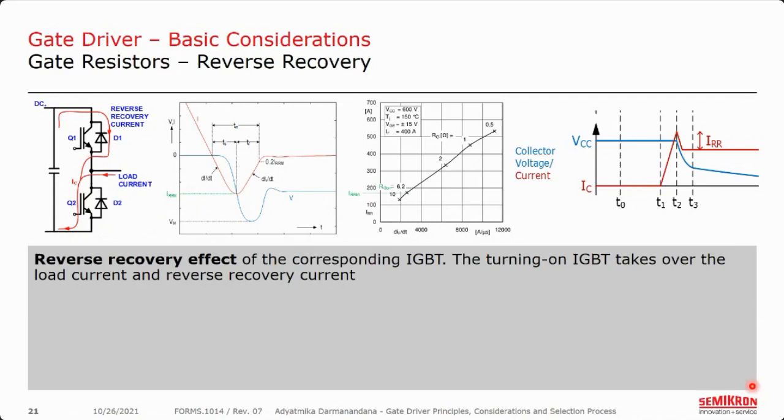If we take a look at the IGBT Q2, the current will be reflected into a peak at the end of the ramp up of the collector current, as we see here in the right curves. We understand that reducing the switching loss requires a lower gate resistor to make the gate charging faster. This approach is limited by the fact that the maximum reverse recovery current and its slope depend on the RG on, as we can see in this diagram. Lower RG means faster slope, but also higher reverse recovery current, which will also increase the power dissipation in the freewheeling diode.